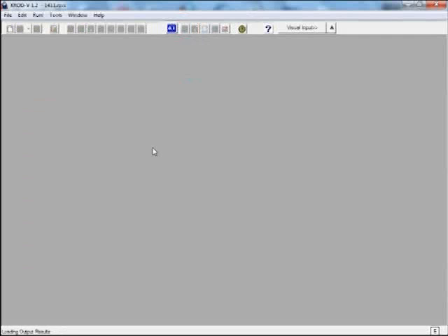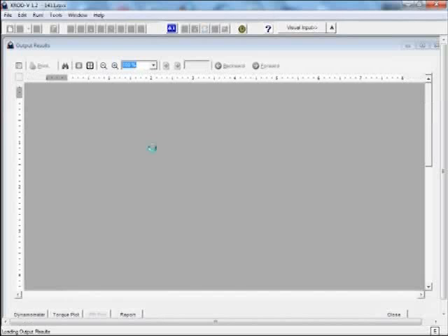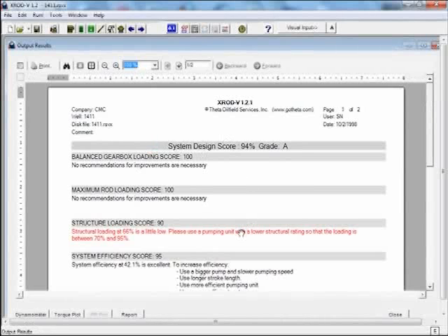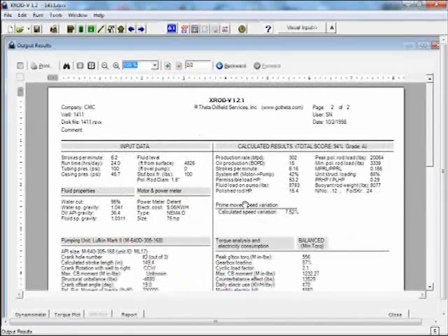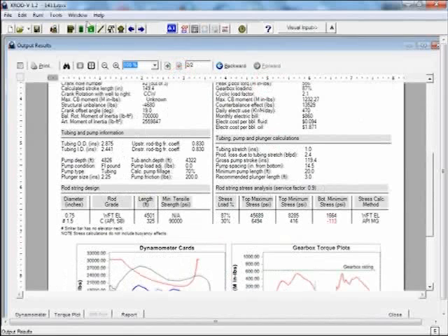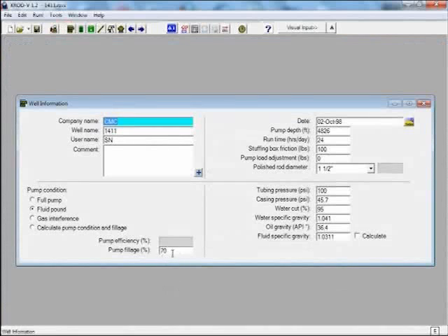Actually, this is a Mark II pumping unit, and we have found that for Mark II units, sometimes the worst fluid pound is actually like around 90% or so. So I'm going to check that to see what happens around that fillage. Again, let me check my single bars. They're still okay. Go back again. And I'm going to put 80% fillage. Run it again.